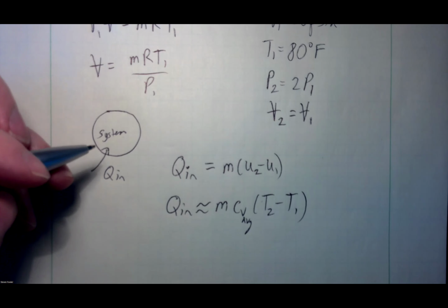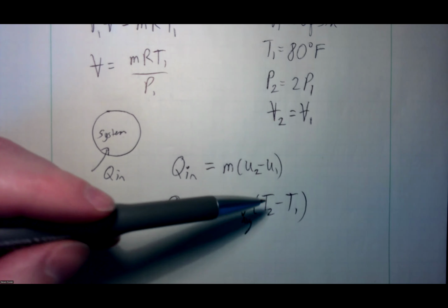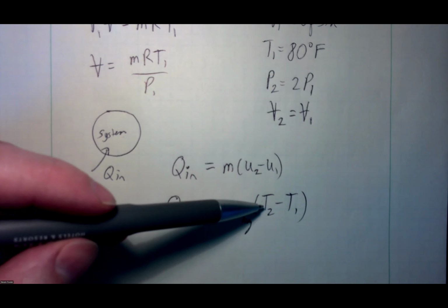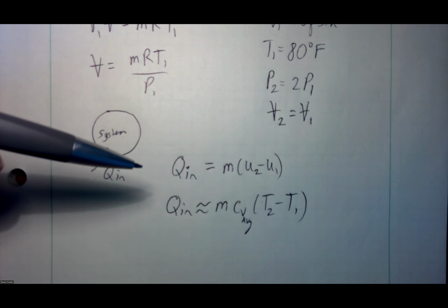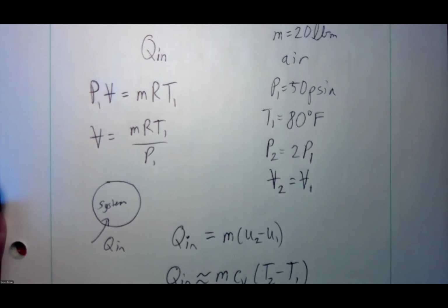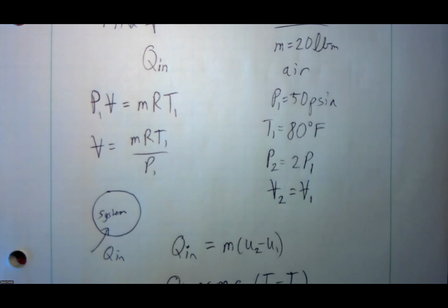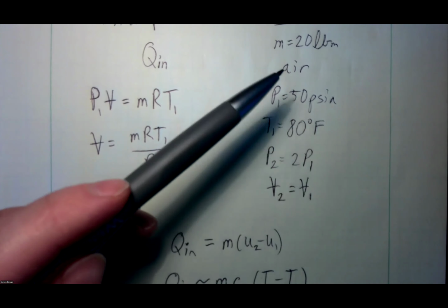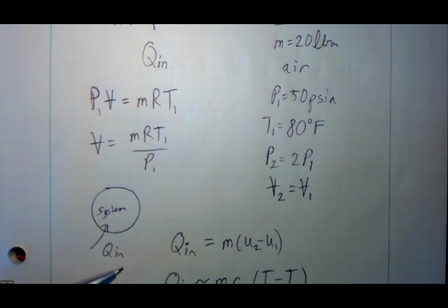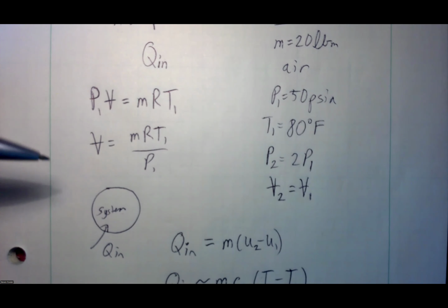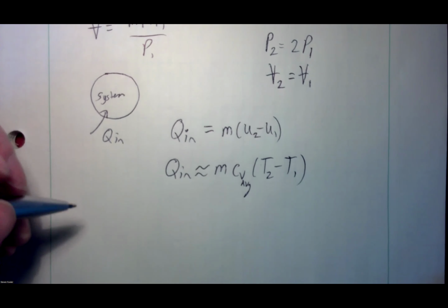Well, what is temperature? Temperature is a property. So now temperature becomes my unknown that I'm after. All right, what tools do I have to find an unknown temperature? Because I've organized everything I know. So what's a good tool for finding an unknown temperature? Well, temperature is a property. I need to know what my substance is. I'm dealing with air. So I need to use the rules associated with air. Well, air is an ideal gas. Oh, I could use ideal gas.